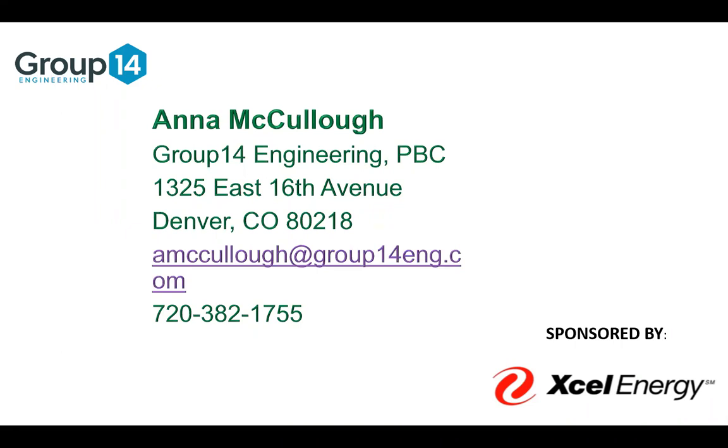Mm-hmm. It sure would be nice, you know how COMcheck is idiot proof. It would be nice if we had a performance software that was idiot proof. It would be, but there are just so many different permutations and combinations that you can have in a proposed design that will affect your baseline design, that there's really no good way to have it be idiot proof. I mean, it takes us probably about 2 weeks to get a baseline and proposed energy model up. It's definitely not a quick 15-minute process by any means. There's a lot of different inputs and analysis.